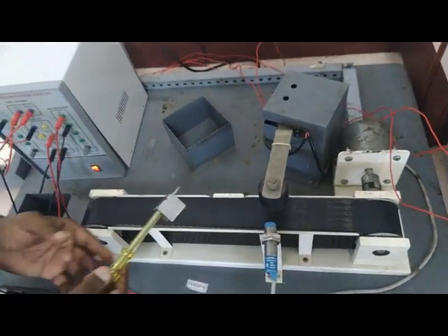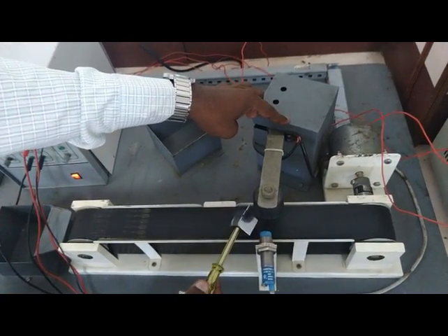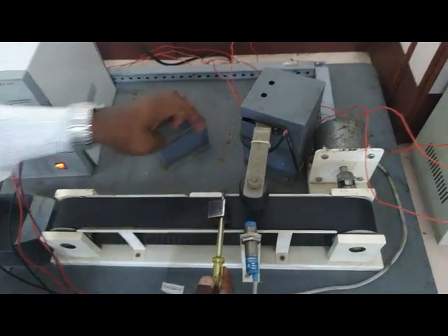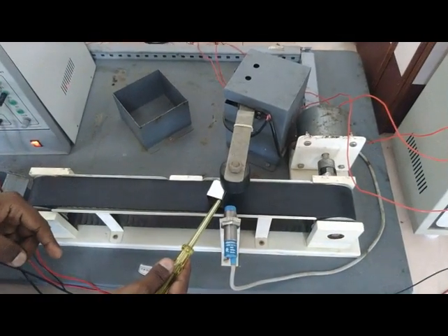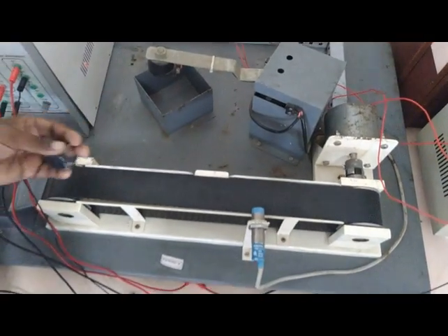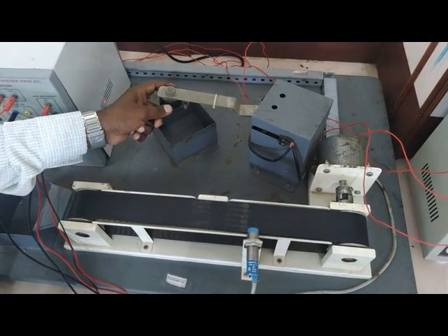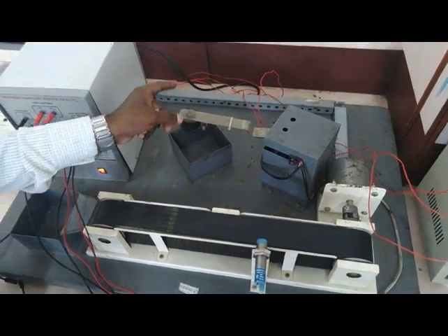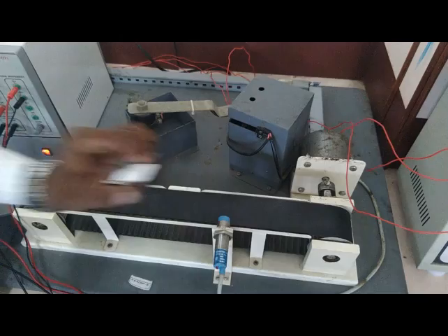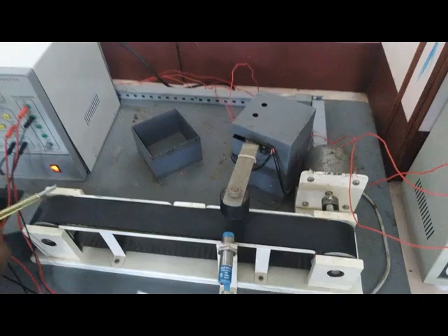Let me keep the material. When I keep it here, the limit switch is already high and the proximity sensor will go high, so that will enable your end effector as well as your reverse direction. Let me give it. So immediately, that's it. These are all the constraints we have. When it is in forward direction, we are supposed to save our energy, so we are not enabling the end effector. And once again, when the material is not available at the starting position, I should move forward and look for the next material, right?